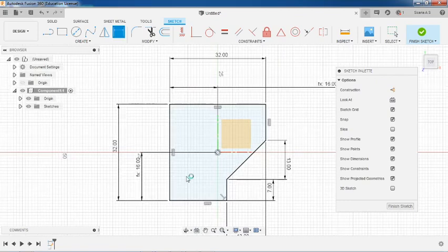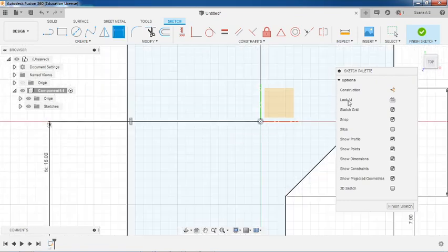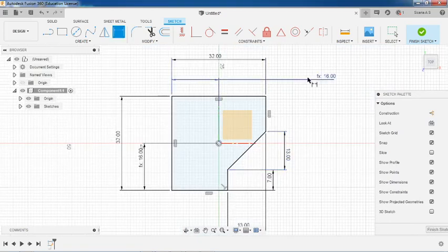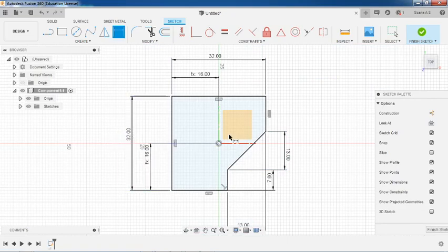As I told you once again, all the exercises I'm going to centralize, and all these exercises are given in the third angle projection. That means the top view will be placed at the top, front view at the front, right side view at the right side, left side view on the left side. So in all the exercises, you have to complete the third view also. You have to draw how the third view will look.